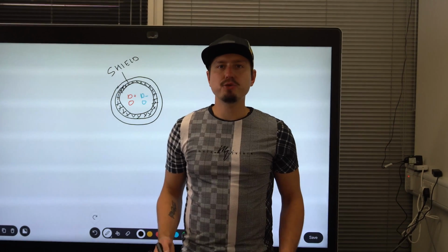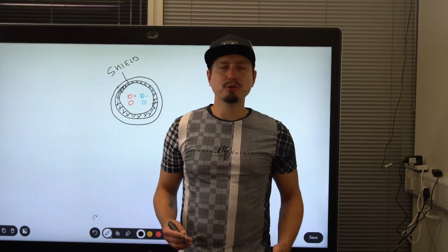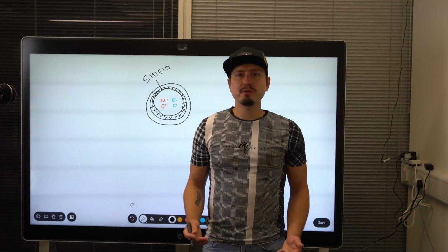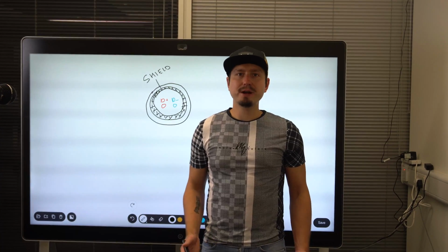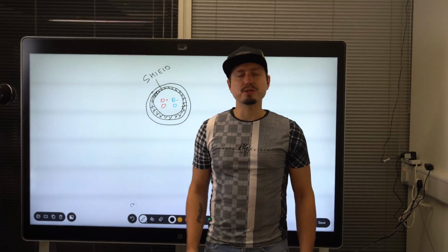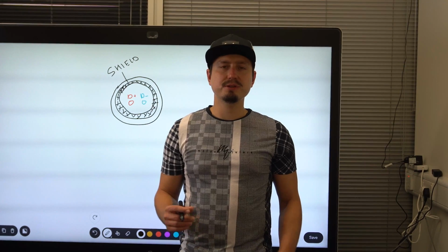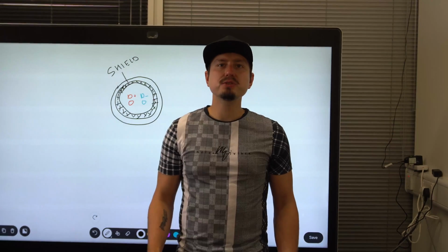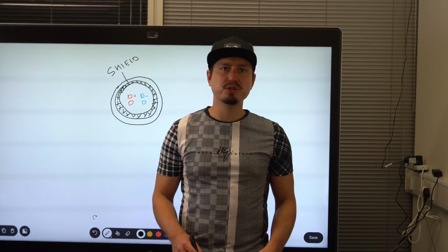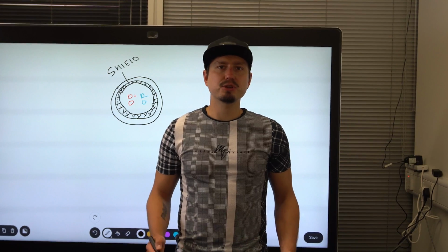Then you must also make sure that the metal enclosure around your printed circuit board has paint removed at all points where it makes connection with itself or the circuit board. Otherwise, it will not function as a Faraday cage and it will fail in improving your immunity and containing the EMI sources. To improve the connection, you can also add a conductive gasket between different pieces of the enclosure. To test for that, I always take out a multimeter and make sure that I have a buzzing connection between different metalwork points and the PCB, and if it doesn't buzz, then it's as good as no shield at all.